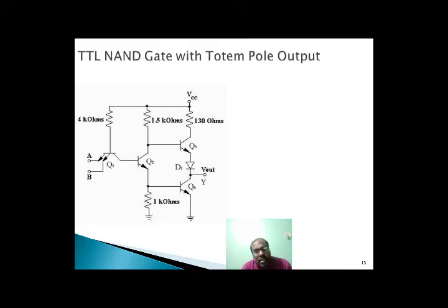There is a current from VCC through R1 to the base emitter junction of Q1 and into the low input, which provides a path to ground directly. Hence there is no current into the base of Q2, and it goes into cutoff condition.